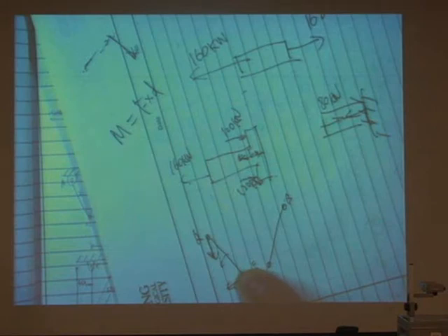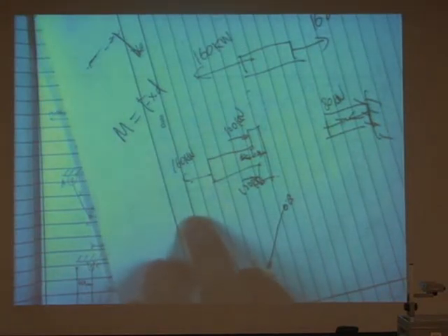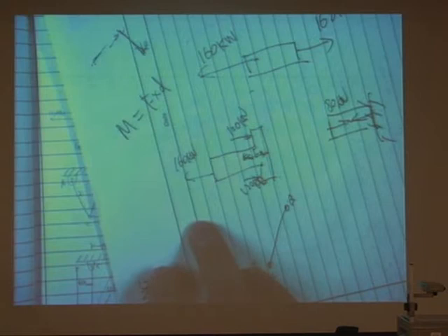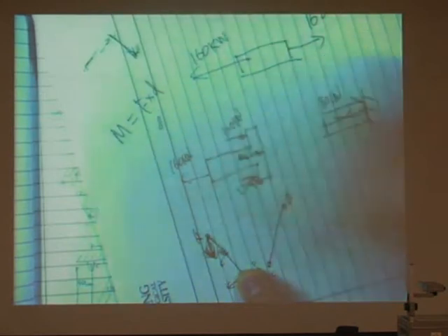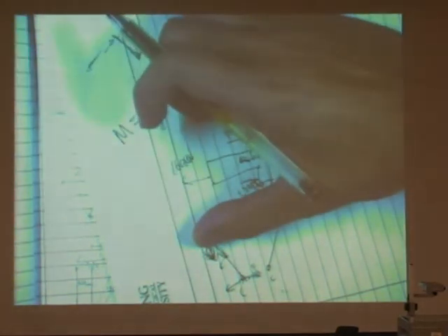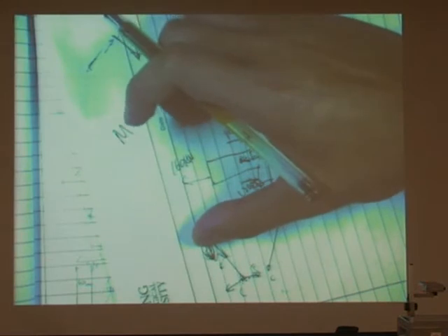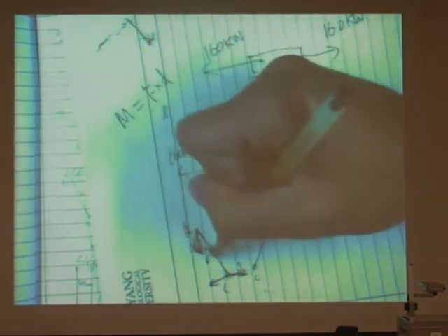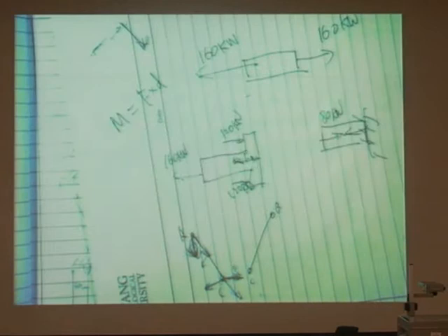So that's why, because it is in static equilibrium, the force must go through this axial direction. See? So then we deduce that the force from this A goes through this axial direction. We can also, in a similar way, take this point A as a point of analysis. Then we know the resultant force, which is the combination of this force FBC and this horizontal force FA, must also be in the axial direction.